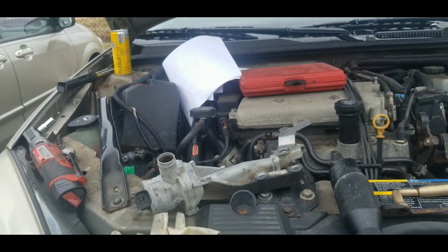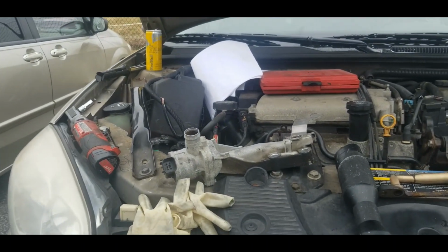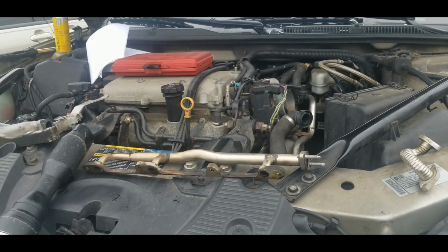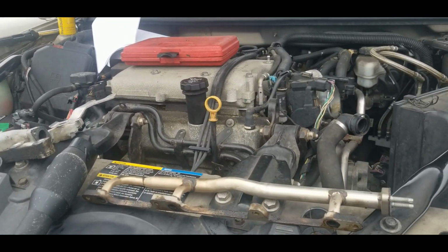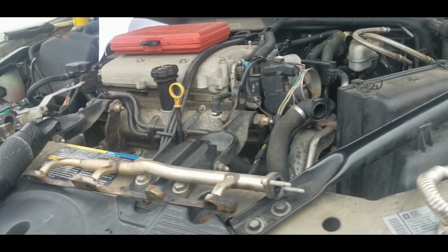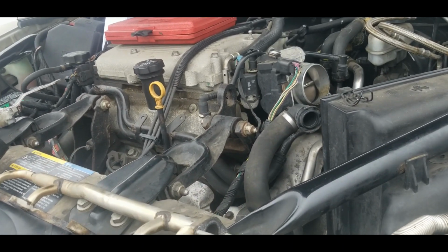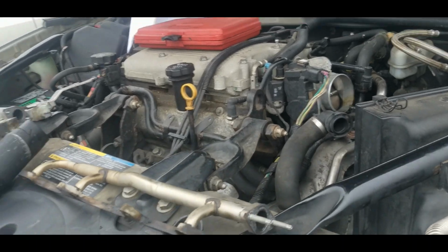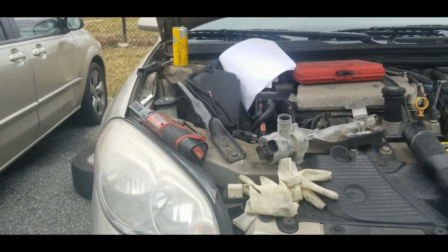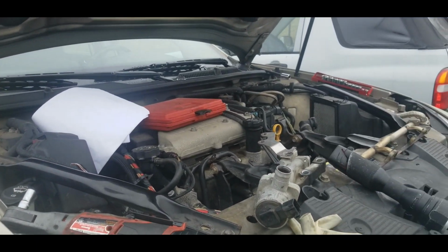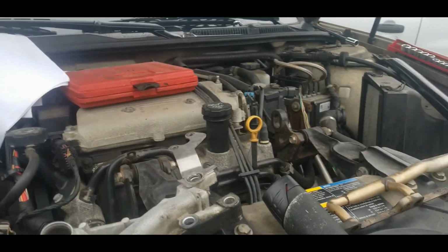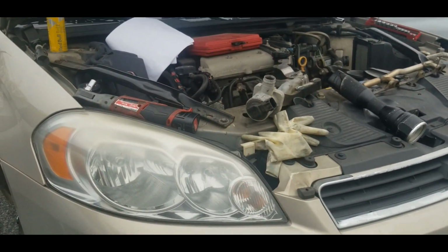So now I'm 99% confident telling my customer to purchase the check valve and replace it. But for now, I gotta install everything back on that I removed, and please don't forget to use a new gasket or use the liquid seal gasket maker, RTV. That would work just fine. So I'm gonna go ahead and put everything back together now, purchase a new check valve, install that, reset the check engine light, and the car will be fixed.